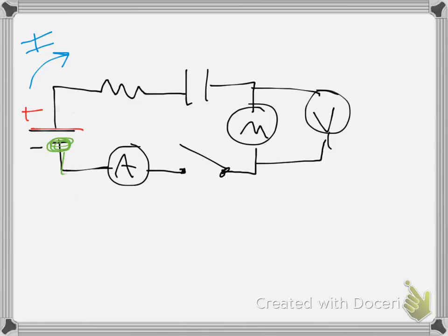So what's going on? What are all of these different symbols? Let's trace. It leaves the positive high potential terminal of the battery, and it goes through the squiggly called a resistor. Resistors resist current. The higher the resistor, the harder it is for current to flow through.